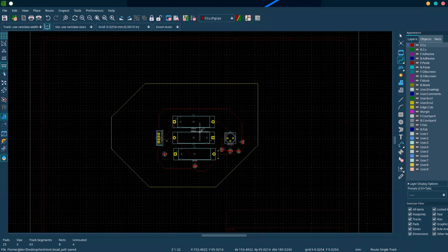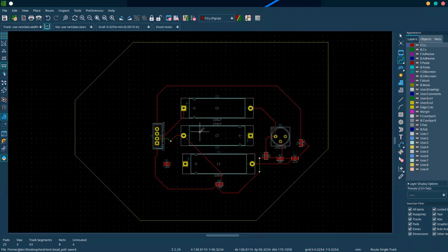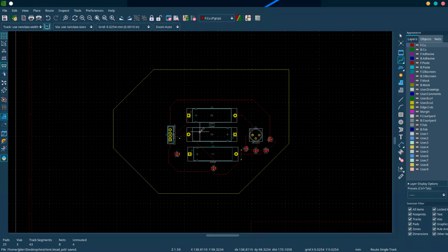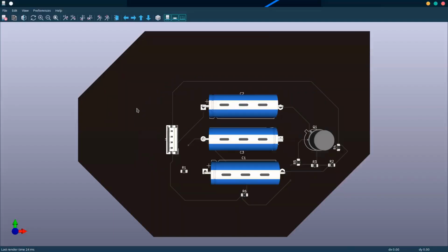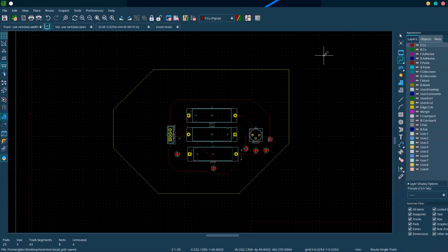Okay, so last couple of things I want to go over. If you look at the board, you can see that it's blank everywhere except where a trace is. Basically what that means is you've taken your copper front plane of your board and you've etched away all the copper, except in the places where those traces are. That's not always desirable because fiberglass is transparent. So it would be nice if we could have some kind of shielding for all those traces. And the way you can do that is by defining fill zones.